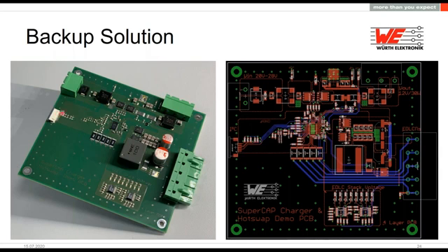So here's the input. Then here's the filtering. These are the MOSFETs, the current sense, and here the output filter. This is the IC from Analog. Here the MOSFETs for the step down, step up, input and output capacitor. Also the current sense for the switch, and here the supercapacitor bank is connected.